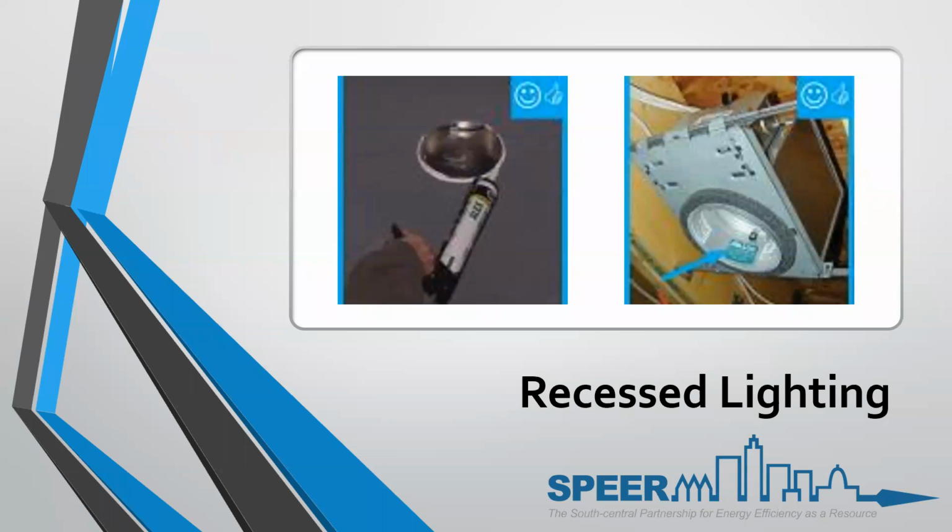So these cans have been tested as per the requirement of code to be tested at no more than 2.0 CFM of air tightness at 75 pascals. That's more than a blower door. That's commercial tightness, not residential tightness or air infiltration side of it. But the gaskets should exist. If they don't exist and you don't see them at pre-drywall, then it needs to be caulked to the sheetrock once it's installed.